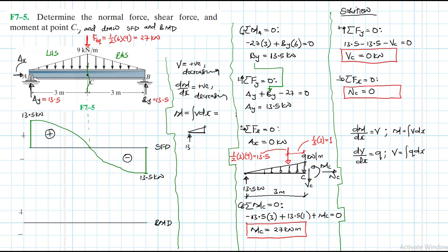So if we wanted the actual formula, then we could write this from principles. Do a section at x there, like so, V, then we have a moment like that, right? And then at this point here we have what we're going to call q, and here we are going to have an equivalent force we are calling F, and F we know is at a position from this point there of 2/3 of x.